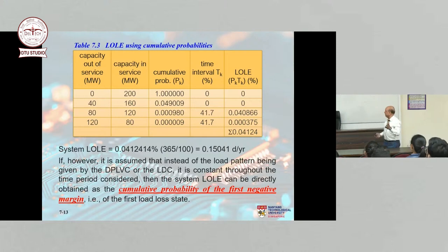So when you are looking at the future planning and you say that the load is like this straight line, somebody can argue, why are you trying to make things so complex? Why not assume the load to be constant? I'm 15 years away from today. Can I say that the load will be like this? Yeah, why not just take a constant value? Take different constant values, find out the implications, and then decide, you know, where you want to stay, how much you want to reinforce the system. That's one way of doing it, yeah.